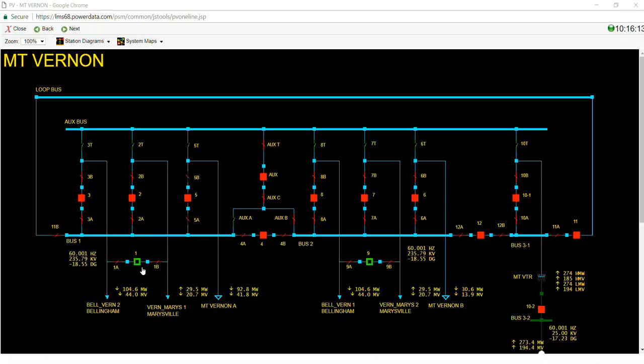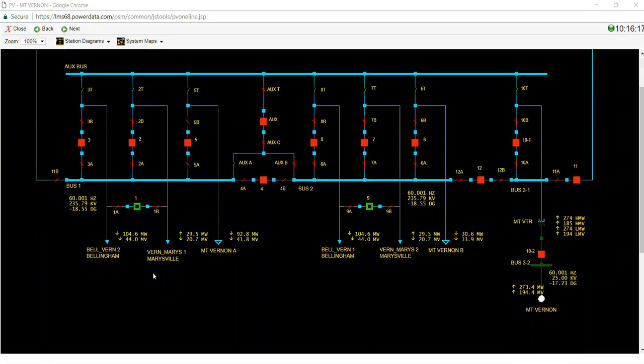In Power Simulator, anytime you see anything that's white, that's an indication that it is de-energized. Of course, the exception to that, because to every rule there must be an exception, are generators. Generators will always show as white. However, I can see that there is obviously an output from that unit, and I can see that the bus it's attached to is in fact colorized green, showing that it is energized at 25 kV.